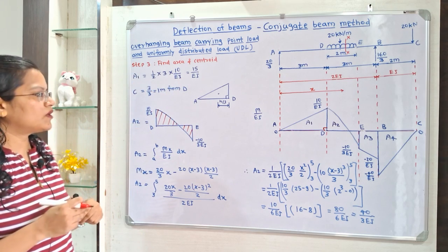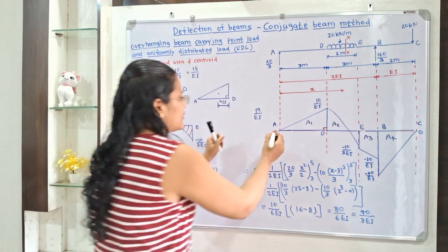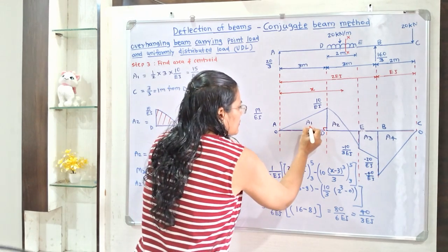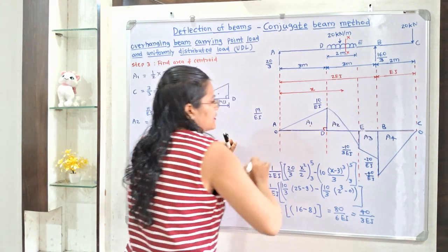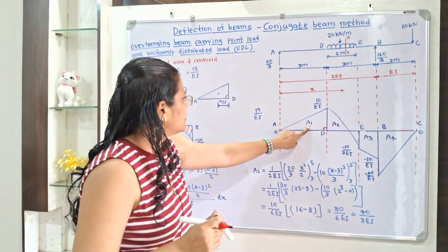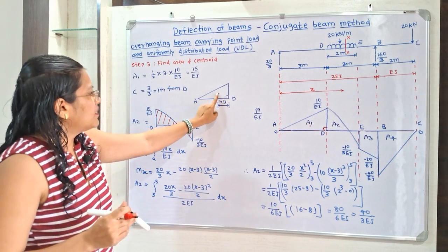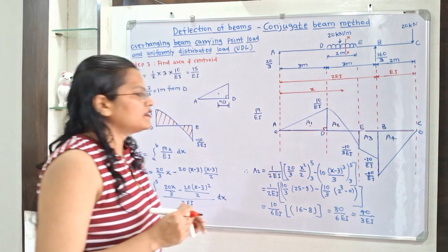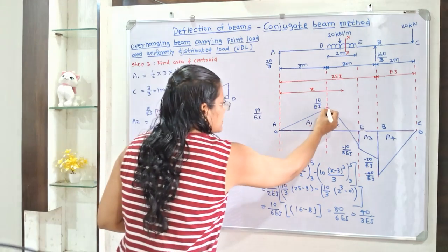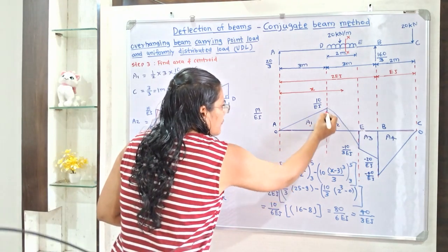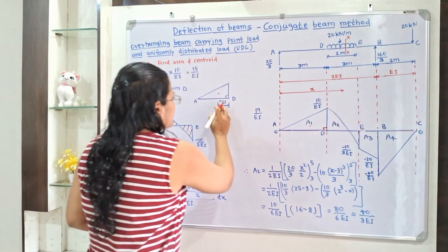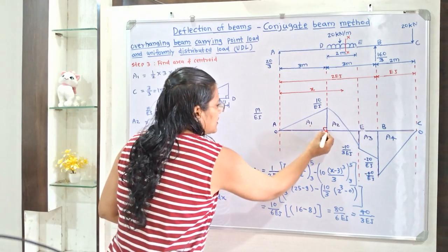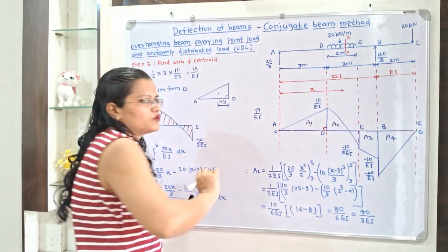Now how to calculate the centroid? We have to measure the centroid always along this horizontal line. Suppose we select the centroid location at this point. Then how to make the partition of this point? If we observe, here is the perpendicular line. From this perpendicular line we have to take the distance h by 3, where the total distance AD is equal to h.